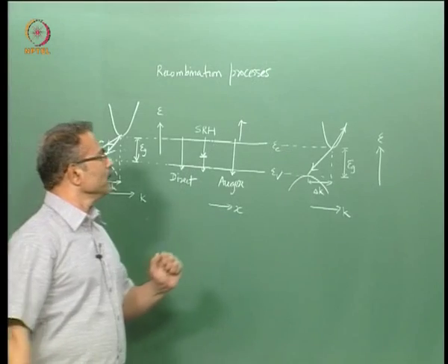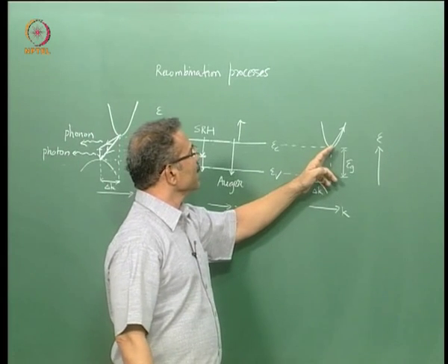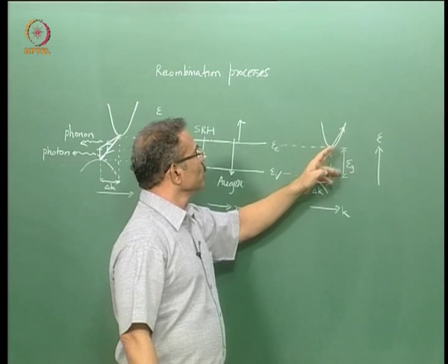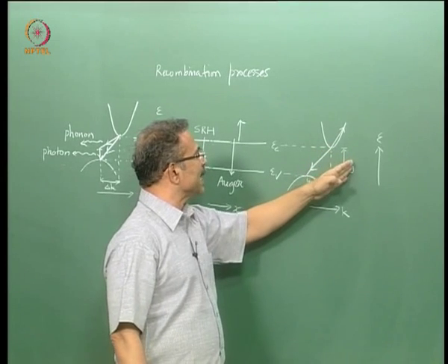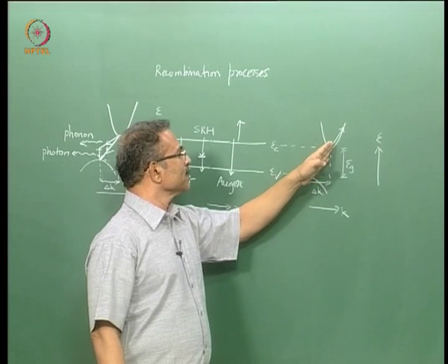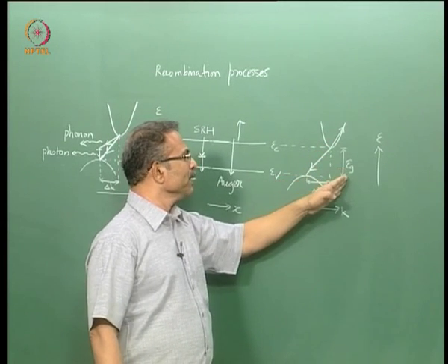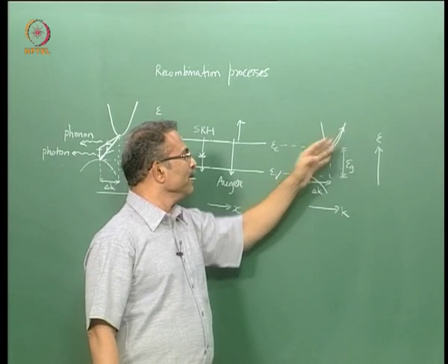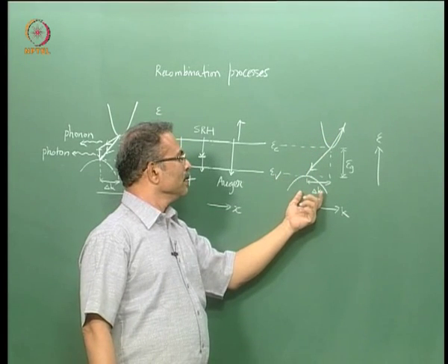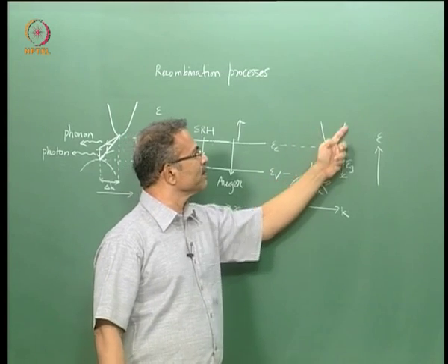Now it may not be possible to find a conduction electron whose energy and momentum relation is exactly given by this Eg versus delta k. That is, if I consider an electron which will take away the energy Eg, the momentum of that electron may not be exactly equal to delta k, because it all depends on the effective mass or curvature of this diagram.